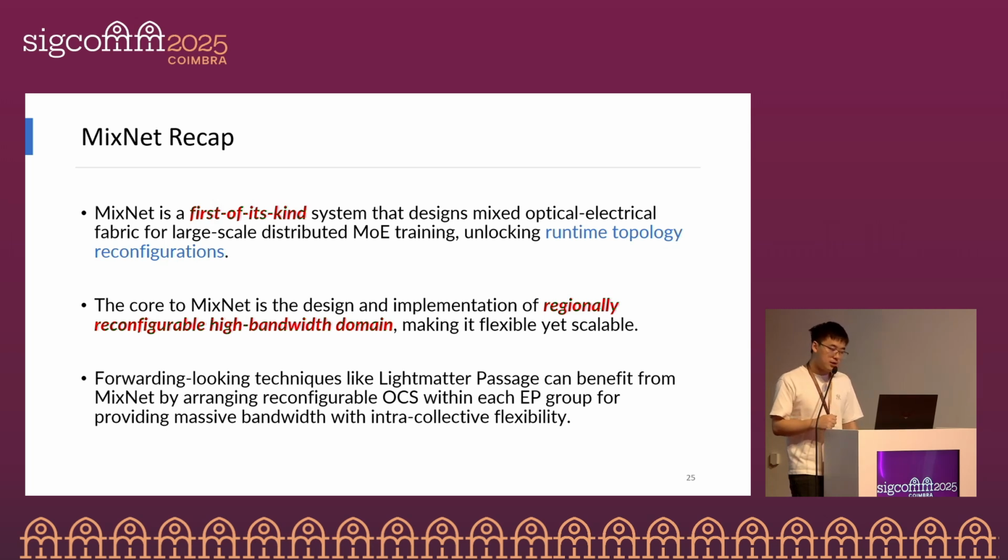We also note that forward-looking techniques like Lightmatter Passage, which is a scale-up optical interconnect, can benefit from MixNet by arranging reconfigurable OCS within each group for providing massive optical bandwidth and intra-collective flexibility.